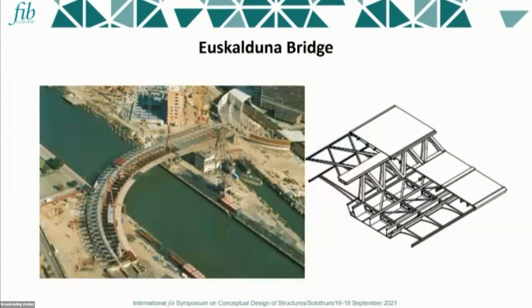But Miguel sent me the drawings. So I found that the roof is not just a roof. These are structural members, because you can see the beam is stiffer in the lateral direction in order to suppress the lateral deformation of the truss.